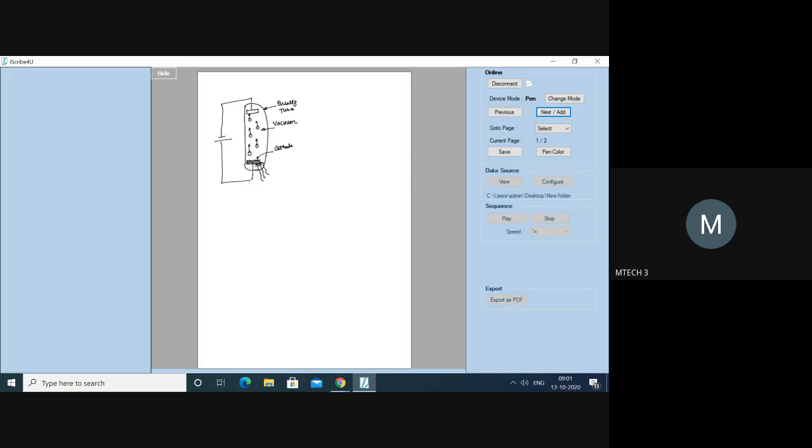Therefore, this movement of the charges gets collected at the anode, which results in what is called the anode current, which is measured here. What is it that you are measuring now? You are measuring the anode current. So this anode current is the measure of light intensity. So this is a simple case.